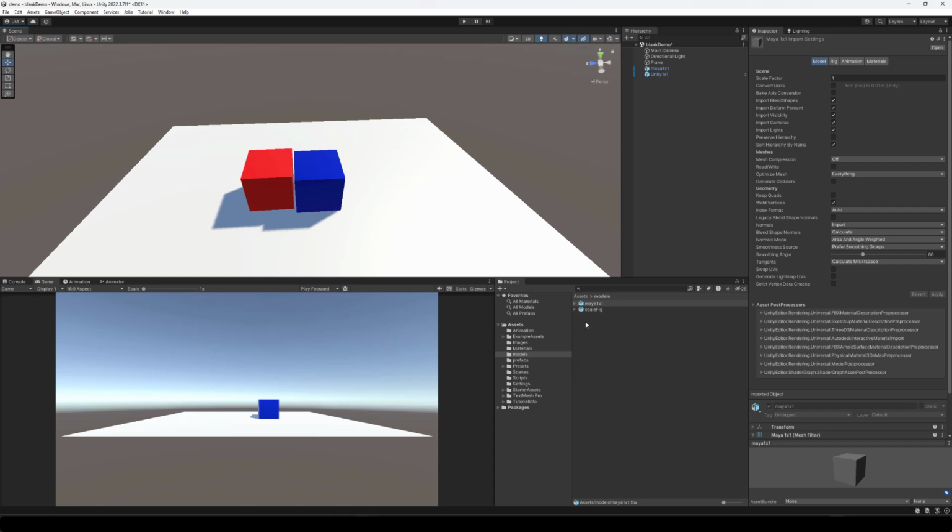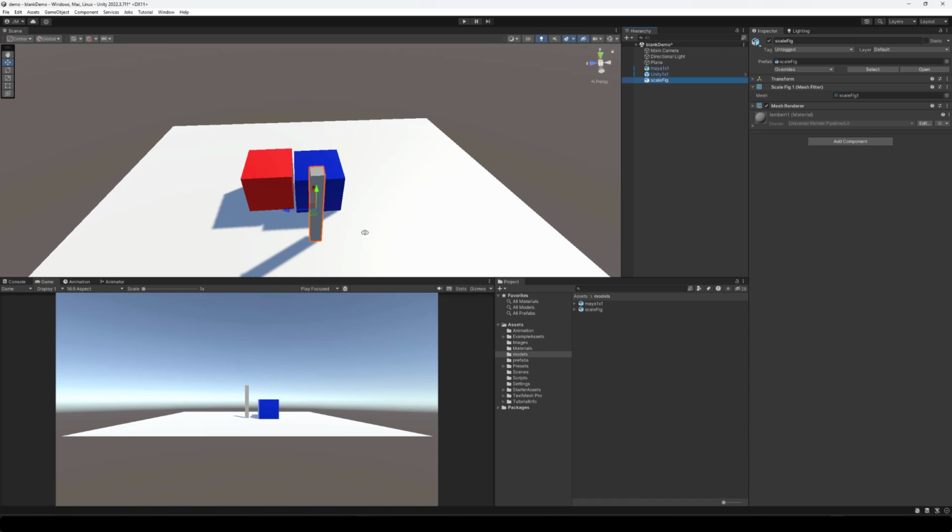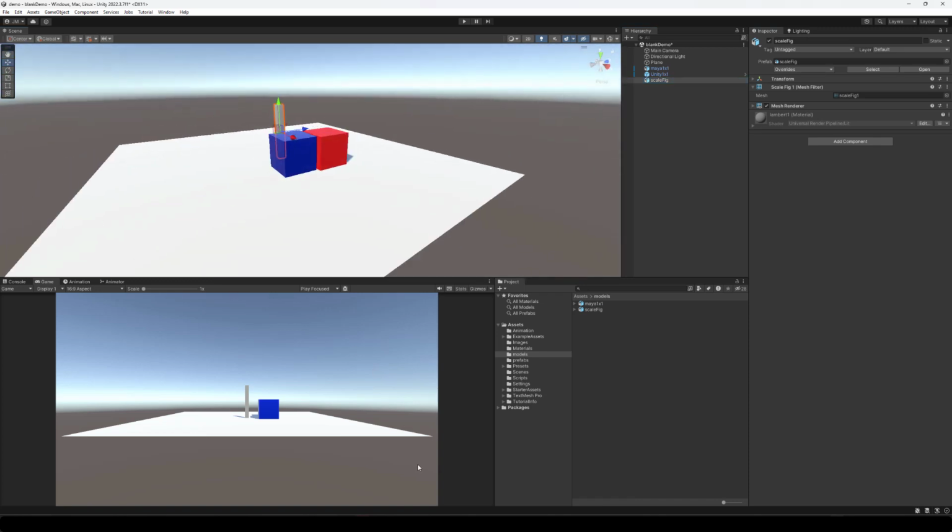Create a prefab of this thing. And in the inspector, don't forget to uncheck Convert Units. Feel free to make a fancier one where there's a sphere at the top or anything like that, but make sure that the total height is about 1.75 units.